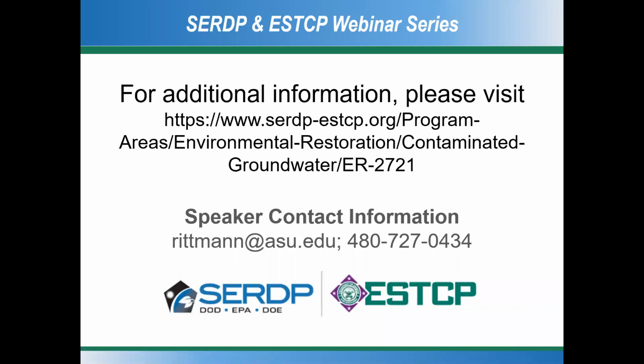The second question is, could they be deactivated by something? Because we all know that there are things that will deactivate catalysts. So in our work with the TCA and TCE and with dioxane around, we found absolutely no evidence of any deactivation in this system. We operated the systems for many, many months. We never had to reactivate or clean or do anything. So for the system with the TCA and dioxane, the answer is no, we don't really have any evidence of any deactivation.